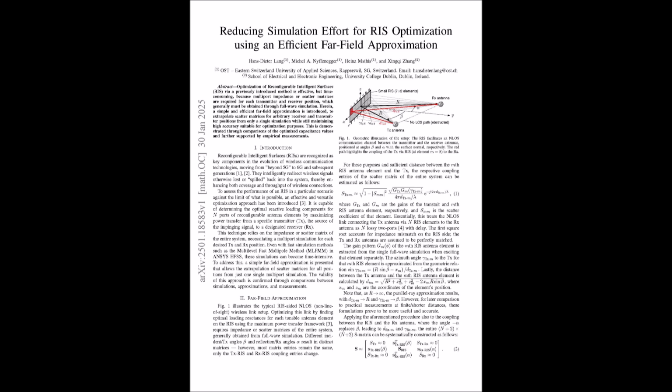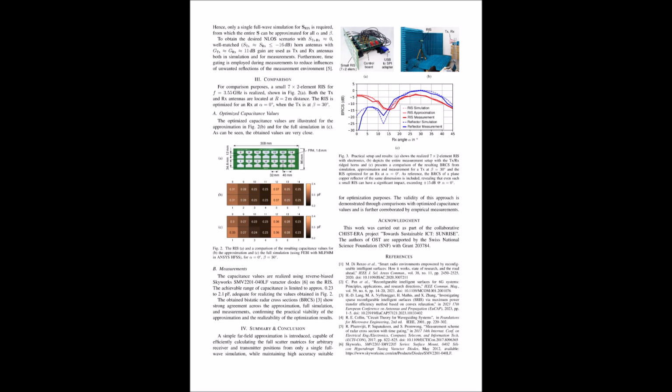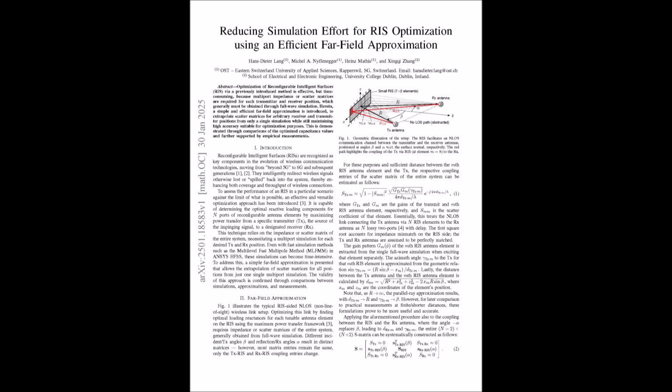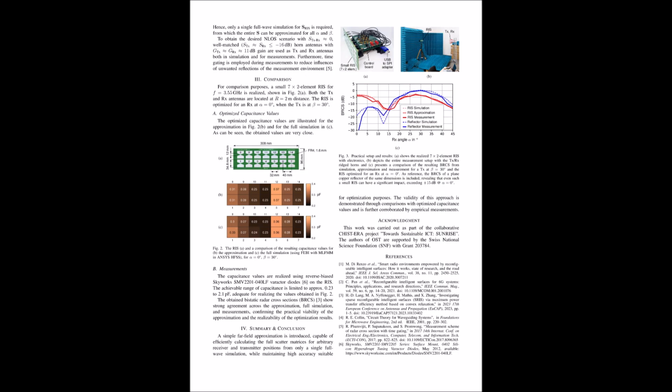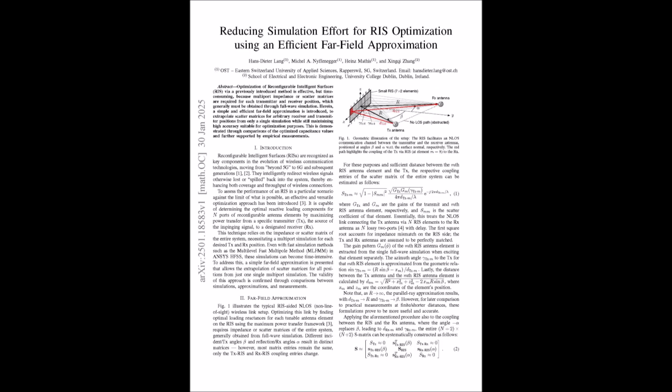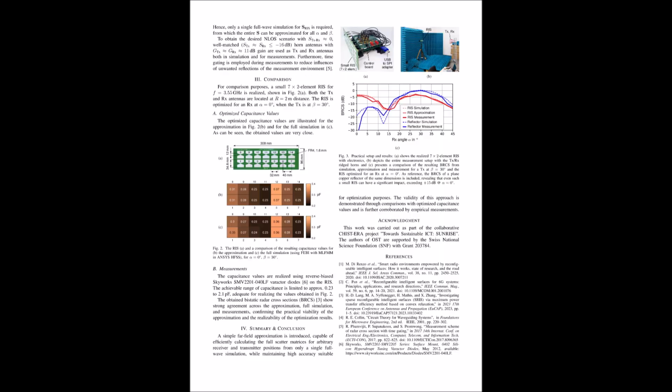What's going on here? Well, the core idea is that they're exploiting the principles of far-field analysis. When you're far enough away from the RIS, those complex wavefronts coming from the transmitter essentially start to look like plane waves. Right, yeah, we talked about that simplification before. Exactly. And this simplification is what allows them to model the interaction between the transmitter and each element on the RIS as a straightforward two-port network. Okay, the lossy two-port concept. Got it. But how does that translate into this equation?